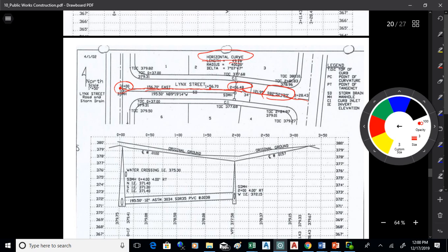That's south 82 degrees, 52 minutes, 13 seconds east, which tells us the direction on a compass. And that runs us down until we hit this other center line at 328.43 feet down the line. All right, so that's the reference line for the road.